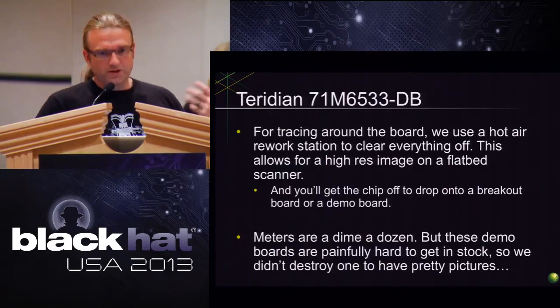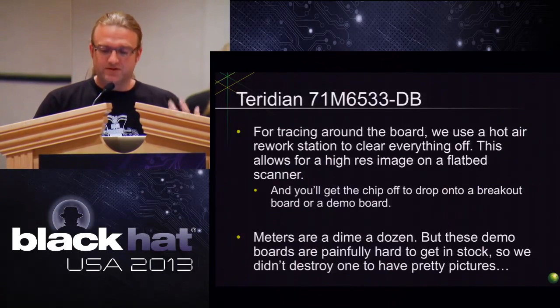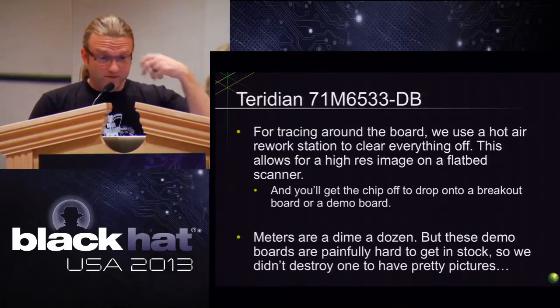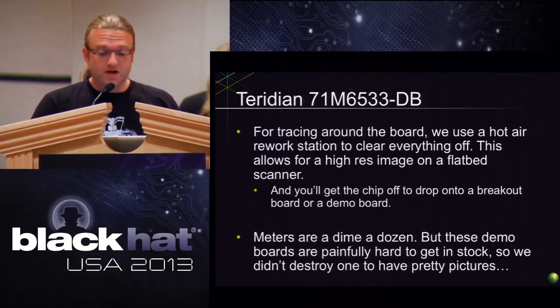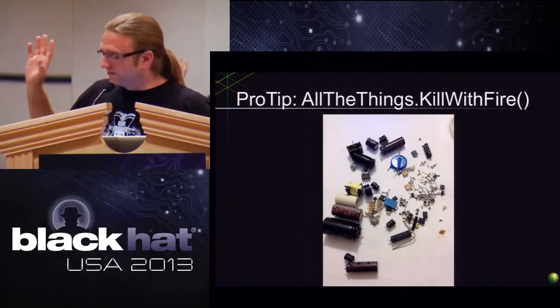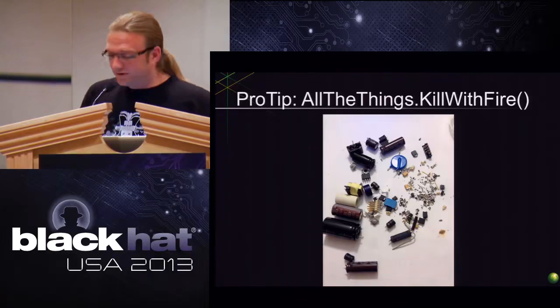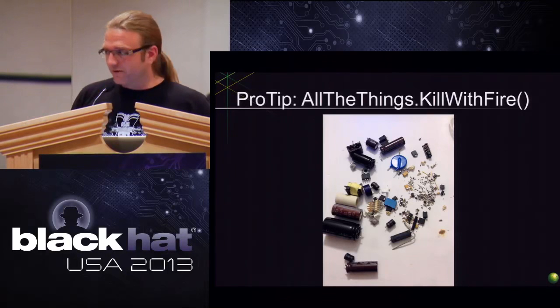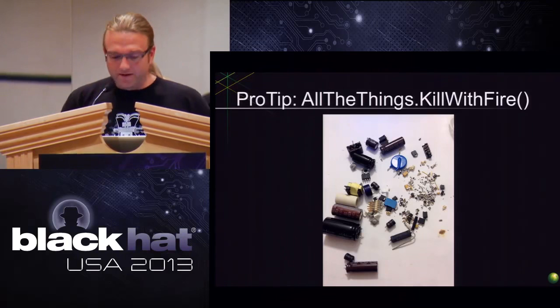Second thing, when you start wanting to look at these type of devices and how they work, you really want to figure out what the PCB is doing around the SoC just as much as you want the SoC. One of the tricks that we have started to do more and more is I take a board, like a production board, and I desolder everything. That's all the detritus that was on the board. I'm sure it's important for it to run, but I don't care at this point. I take that, I throw it away.